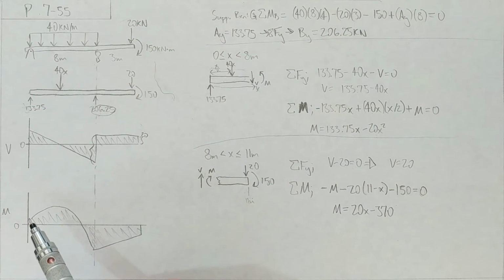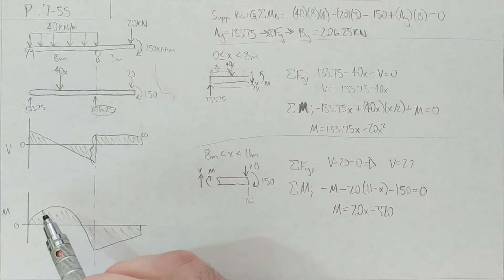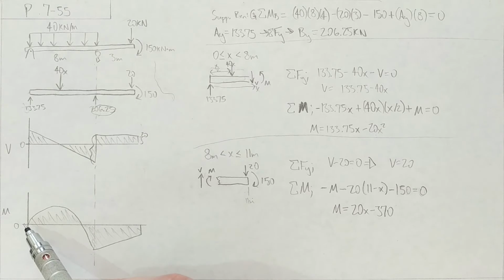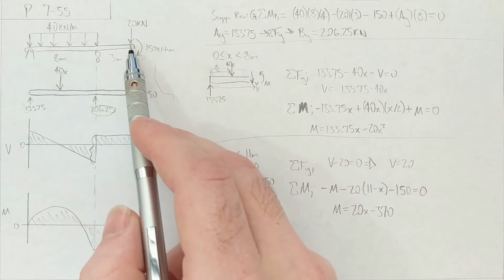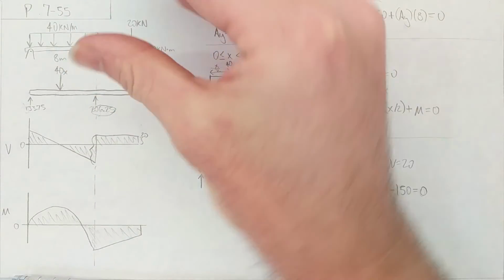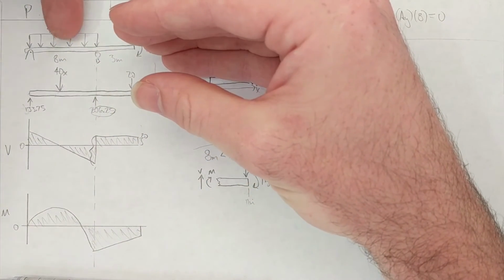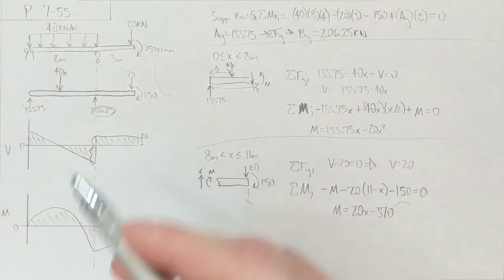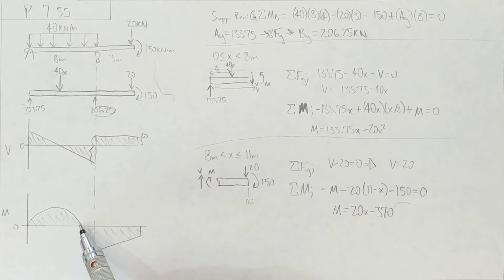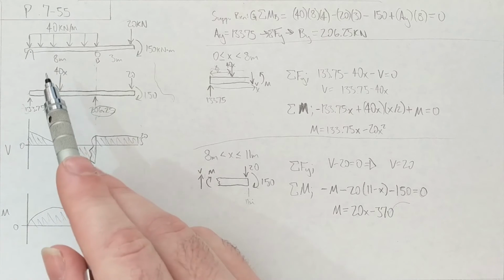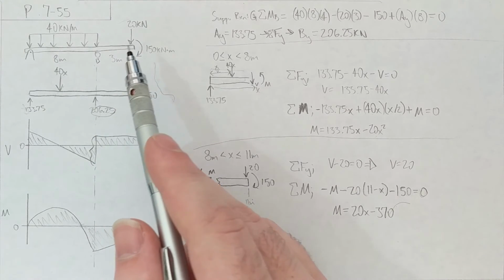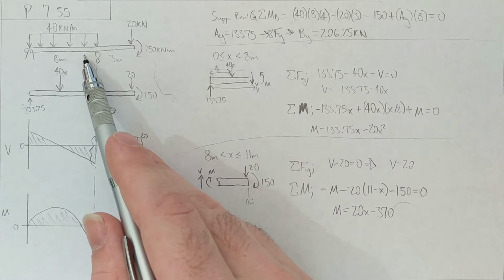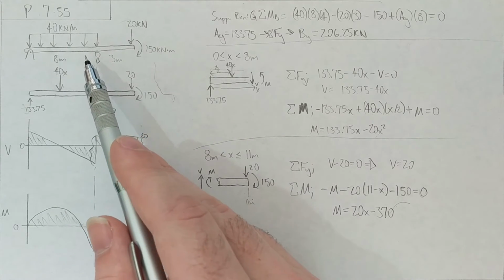All right, now down into the bending moment. This is going to be quadratic, okay? And you see that these forces over here are bending it this way, right? Whereas this force here is pushing it down, and they're sort of bending it around B. What's cool about doing these kinds of diagrams is you see this zero crossing, wherever the forces from this side and the forces from that side cancel out. It's actually a little bit to the left of B. And this is the kind of thing that's really important when you're designing mechanical components.